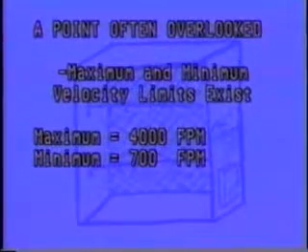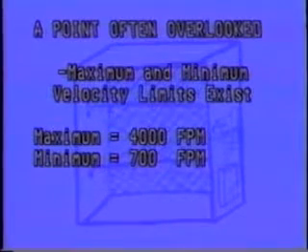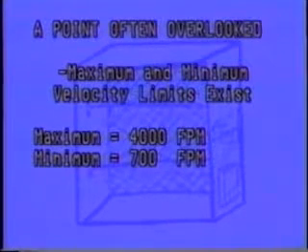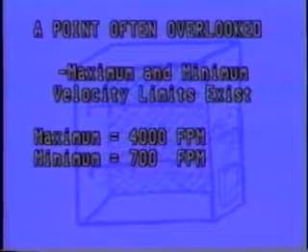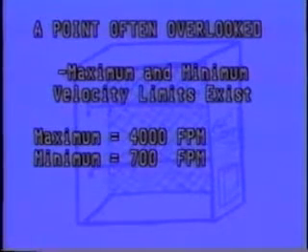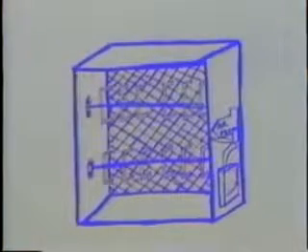These units also have maximum and minimum velocity limits. Above a maximum velocity of 4,000 feet per minute and below a minimum velocity of 700 feet per minute, these units will not function as specified. Therefore, single point sensing of duct static pressures in end-of-duct applications will be acceptable, not to mention much less expensive. However, a point must be chosen where airflow is relatively straight, thereby reducing the possibilities of a velocity pressure component being sensed.